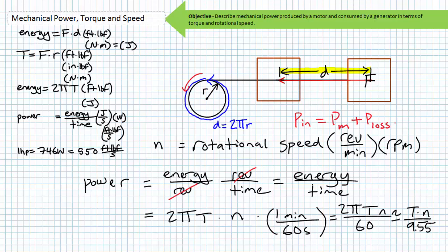Obvious losses include frictional losses from the shaft riding on bearings, and I²R losses in the motor windings because these windings have real, albeit small, measurable resistance and heat up when current passes through them. Not so obvious losses include hysteresis losses, which are magnetic losses in the iron core of the motor, and eddy current losses, which are electrical losses in the same core.